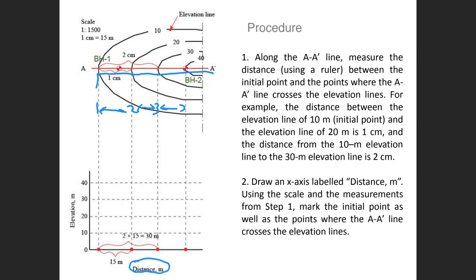So this is what you need to do. You just need to have these numbers along this line that will give you distance in meters, and elevation will be on the vertical axis. So this comes with here. So then for each number along this dashed line, you're going to have a point that will give you distance and that will give you elevation. And that is meters above sea level. Yes, that's typically meters above sea level, that's correct.